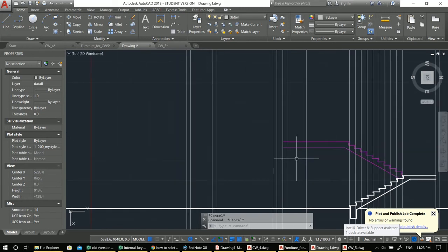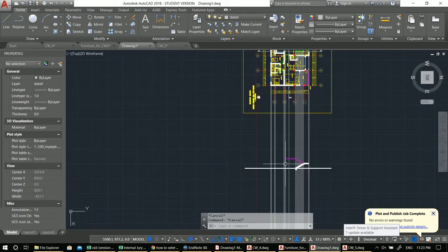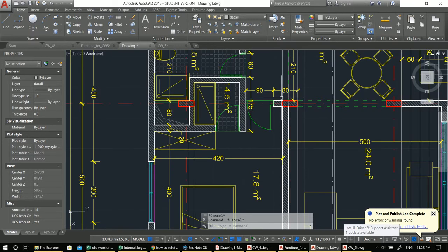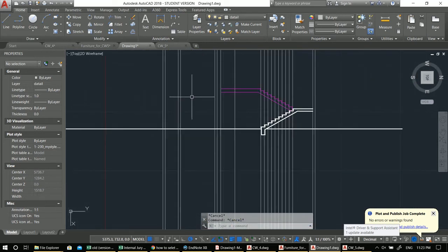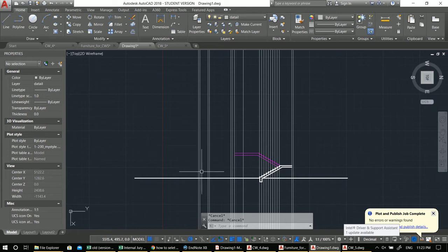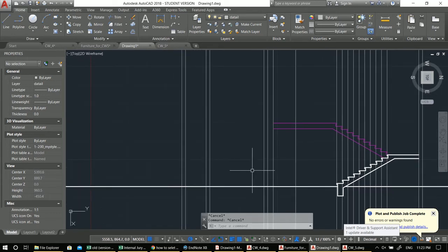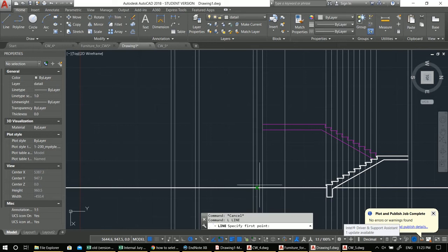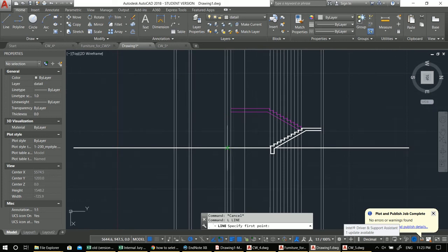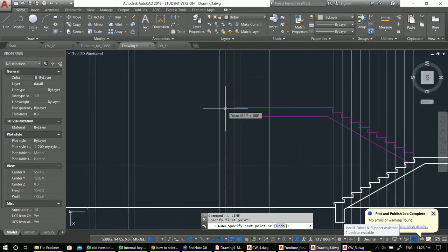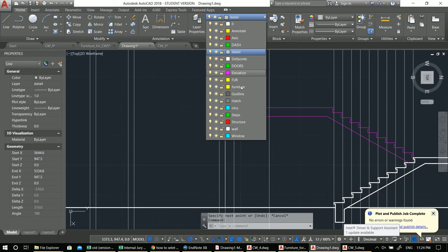Alright, now you have to put the walls where the walls are due. Let's say which part we are cutting here. The elevator will have a shaft. This is a closet, so it doesn't exist on the ground floor. It will start on the first floor. Because I'm planning to copy this, make sure which line is which. So this first line is for the door. This is actually the wall. So the wall comes here. This will go all the way up. It should be in layer wall.